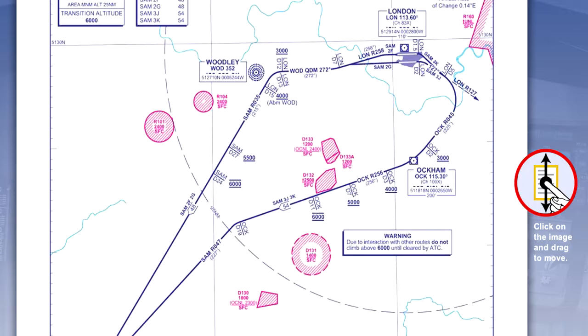Departure procedures, departure routes, and standard instrument departure charts are published in accordance with standards contained in Annex 11 and Annex 4 to the Chicago Convention. Here, you can see a typical plate for a standard instrument departure, more commonly known as a SID plate. Don't forget, all standard instrument departures, or SIDs, start at the departure end of the runway and end at the point of joining the ATS route system.